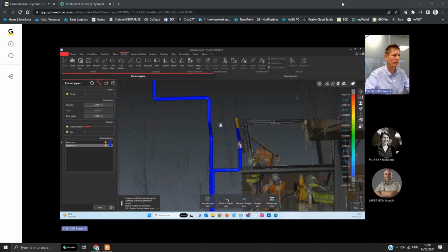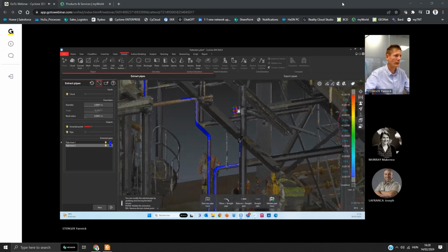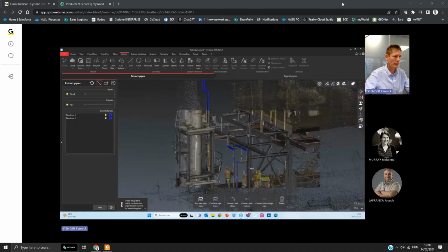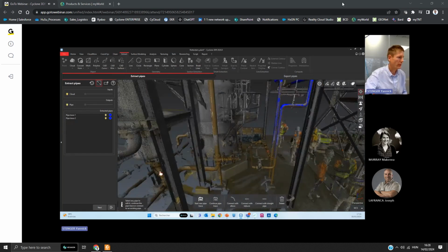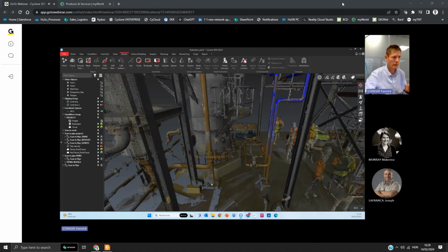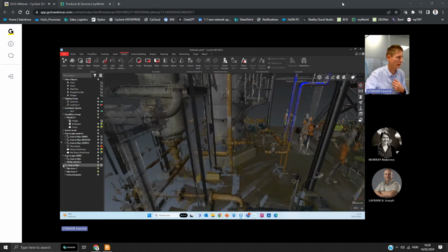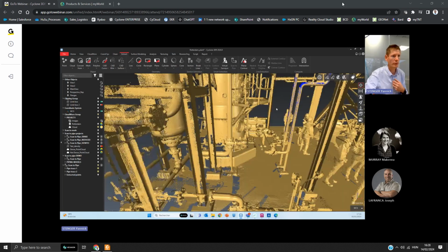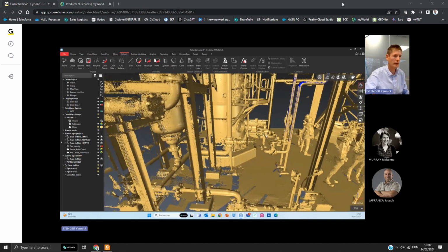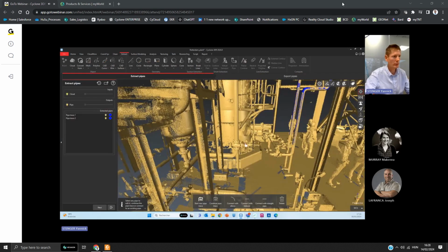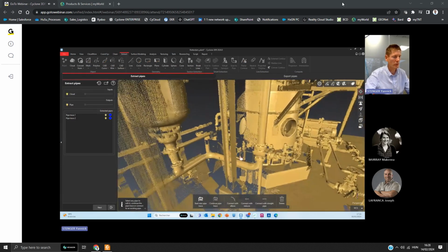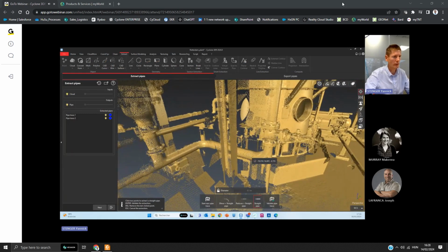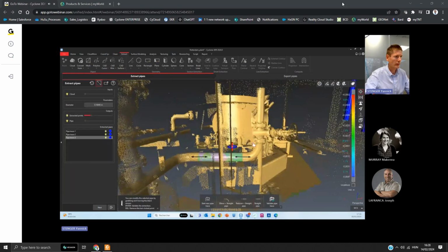It's pretty efficient and fast to do my extraction. I also would like to show you how to create a reducer. Also, it's possible to quit this workflow. So I have my scan2pipe project with my 2 pipes, and I can decide, for example, to change the representation of my point cloud if I have a classification or intensity, and I can open again. It might be a tip. For example, the smooth representation might be a good one, very appropriate for a piping environment. So I have another pipe here.